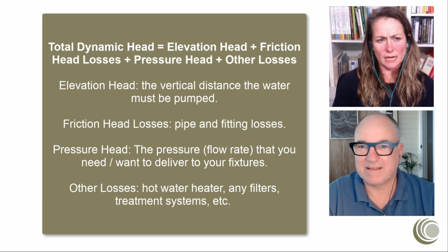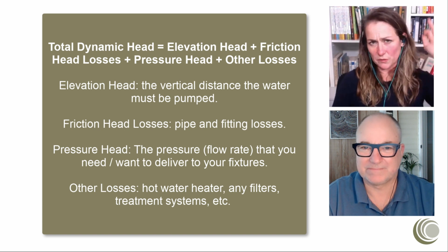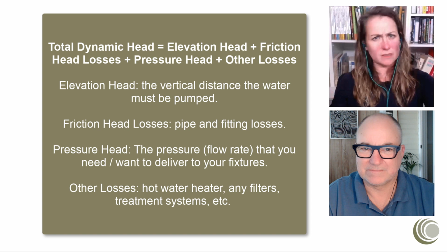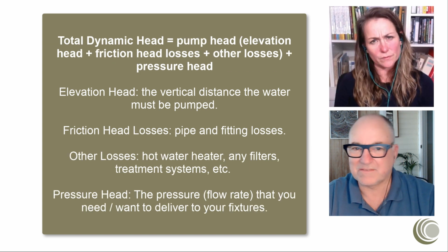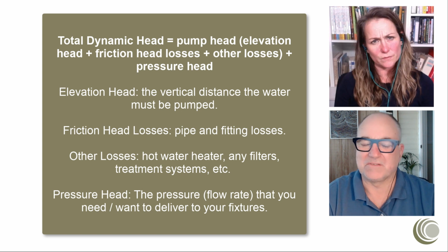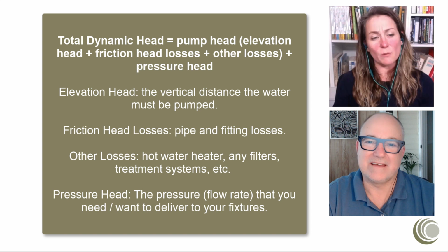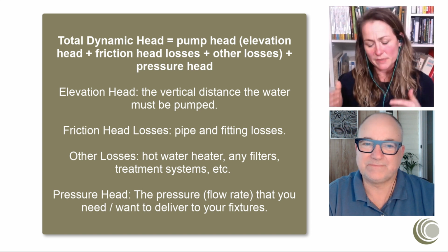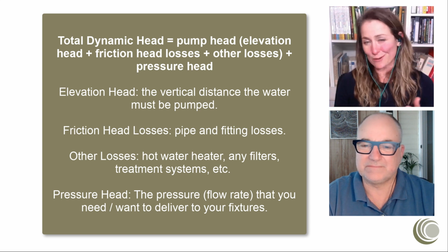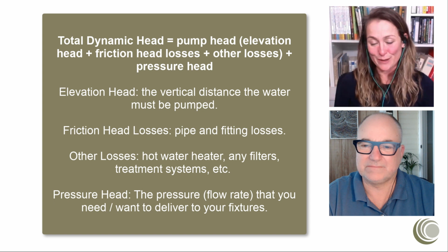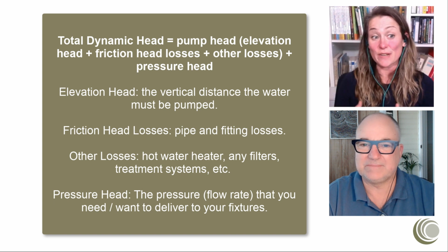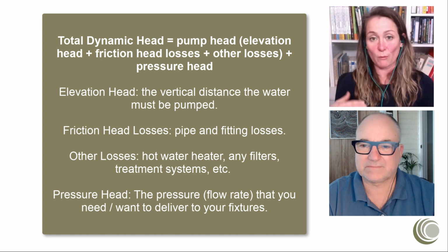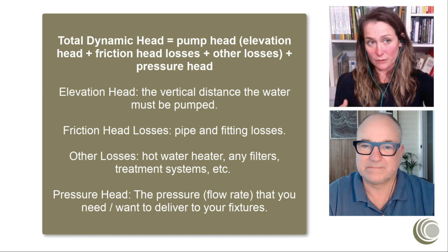So right, an example of that would be a second story of your house, and your rainwater tank is at ground level, something like that, right? Absolutely, and these are the things to consider. And I think you've got a little drafting design module that you've taken people through. Looking at the elevation, where the elevation becomes particularly poignant is underground, buried tanks, right? Because then you're starting to have relatively, possibly significant, elevation head from the point where you're drawing water to where you might be delivering water.